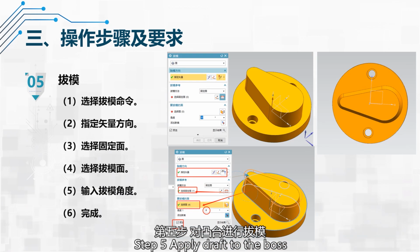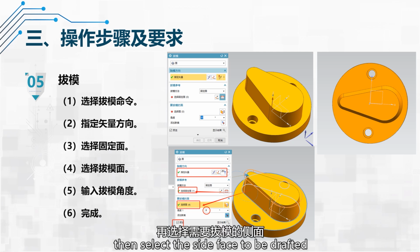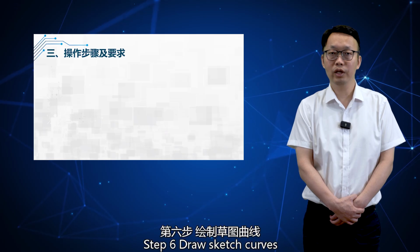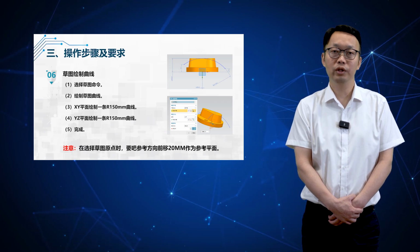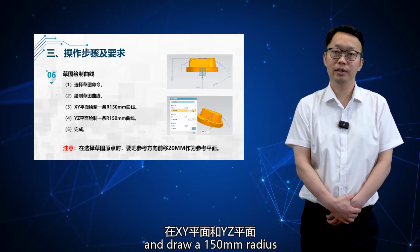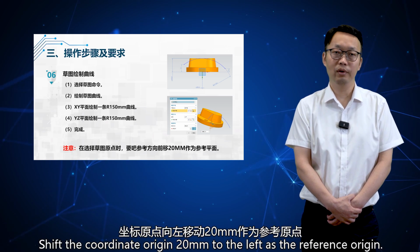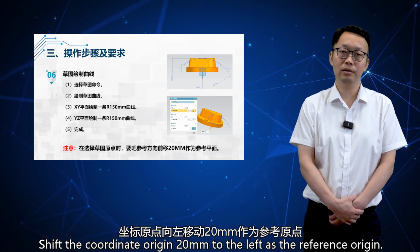Step 5. Apply draft to the boss. Click the draft command. Select the draft vector direction. Choose the fixed face as the top face. Then select the side face to be drafted. Input the draft angle, preview, and if correct, click Confirm. Step 6. Draw sketch curves to split the body and trim the boss. Click the Sketch command and draw a 150 mm radius curve on the XY plane and YZ plane respectively. Shift the coordinate origin 20 mm to the left as a reference origin.